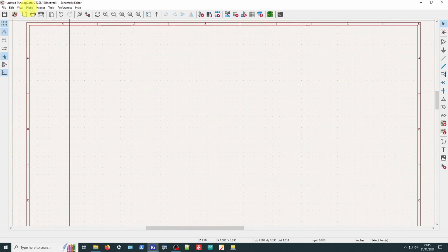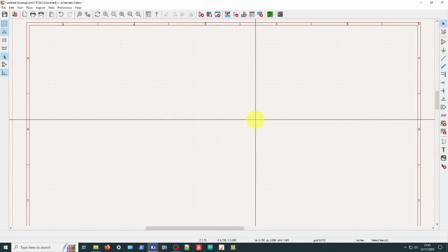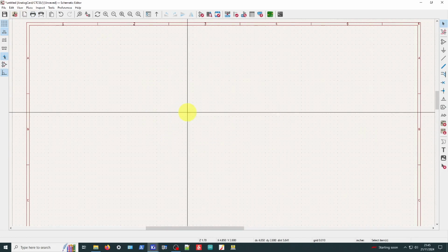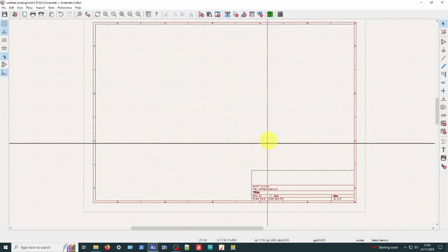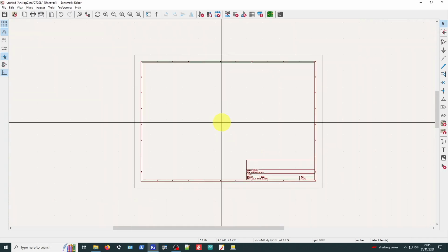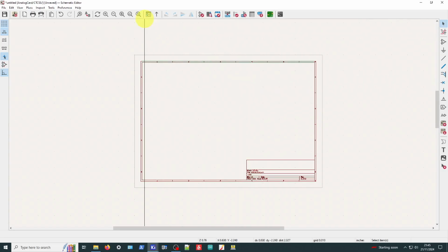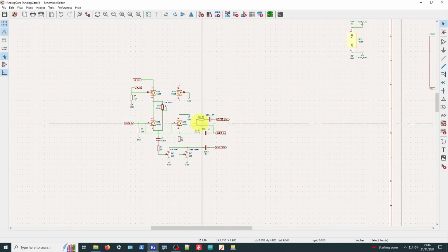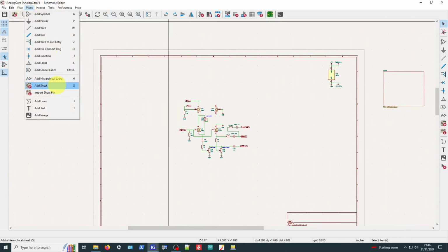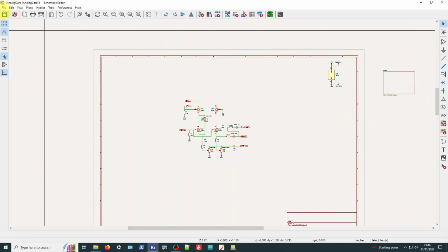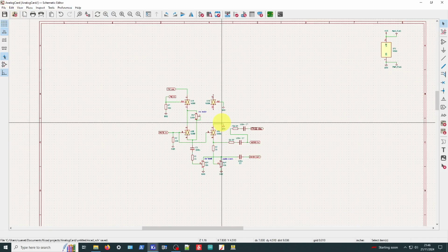And in here, place our components and build up the whole CTCSS circuitry around the Atmel 328P and some other parts, crystal, whatnot. And that could all go on this sheet. So I'm just going to leave this sheet blank and go back to the root. And you do that here, or you can use the little arrow here, which takes us back to the root sheet. And you can have multiple sheets. You can make multiple sheets here just by using place and add sheet. Okay, so I shall click save, and there you go.